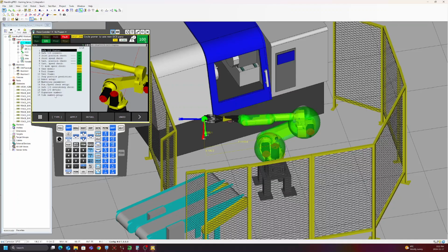And remember, if you forget the code number, you cannot make a change, and you need to call Fanuc to help you with that, and it costs some money. Now we apply the DCS change. Now we will cycle power the robot.